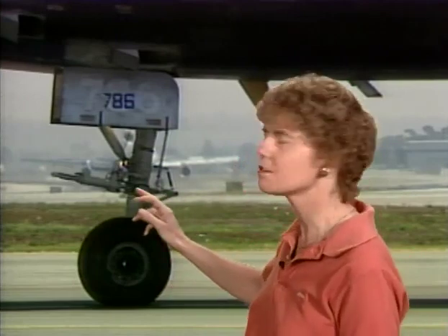One of the things the FAA wants you to know is that if you have a steer damper on the aircraft, it's going to have high-pressure hydraulic fluid on the inlet of the steer damper. And if that high-pressure hydraulic fluid is removed, if it doesn't have high-pressure fluid anymore on the inlet of the steer damper, you will still have automatic damping action.